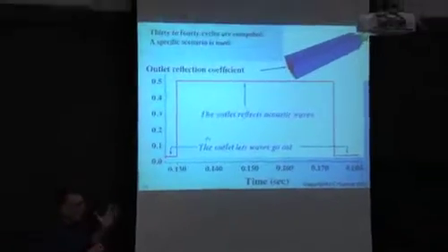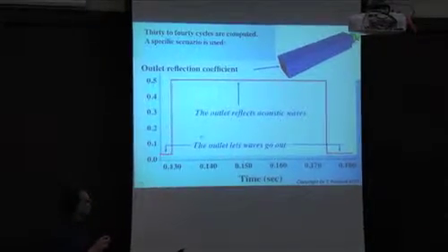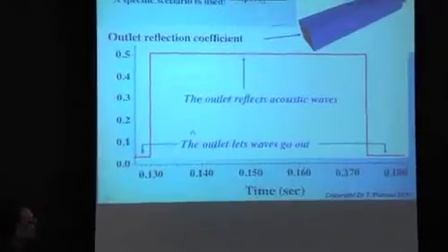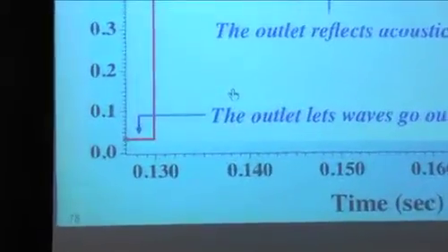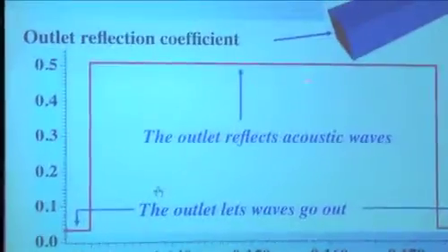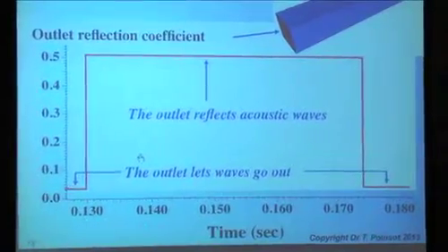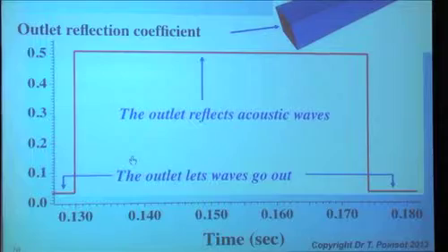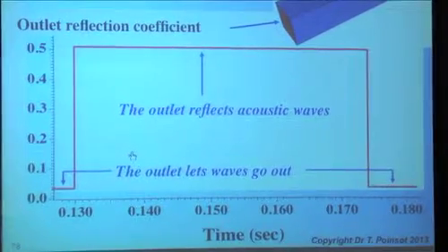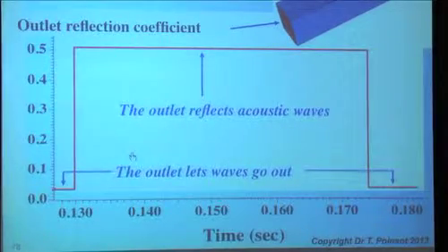So I have a scenario that we built versus time. We will start by having a non-reflecting outlet, then we'll make it reflecting for a certain amount of time, and then we'll make it non-reflecting again. Okay? And it's the only thing we change in the simulation. All the rest, chemical scheme, chemistry, whatever, mesh, everything is the same.